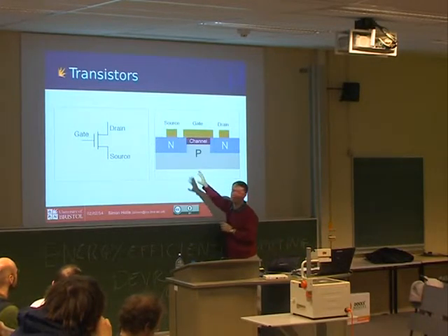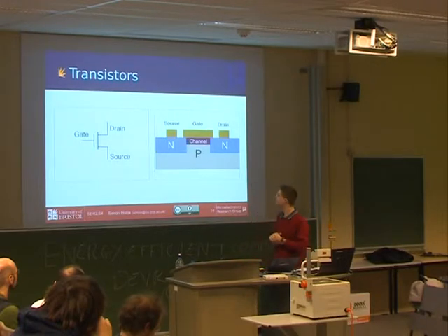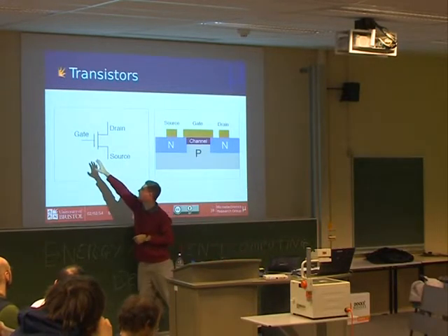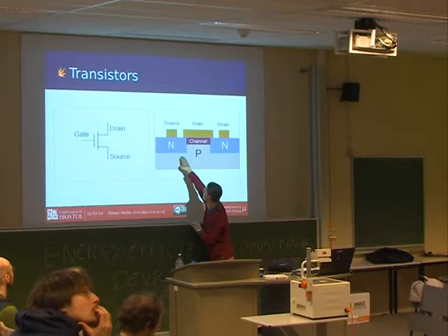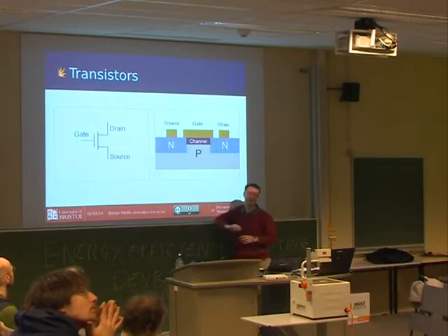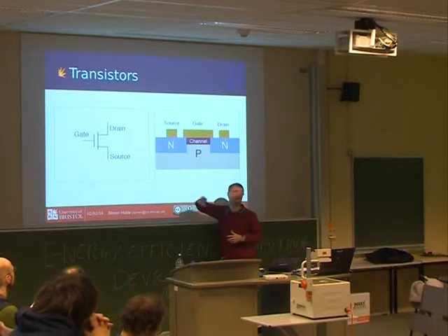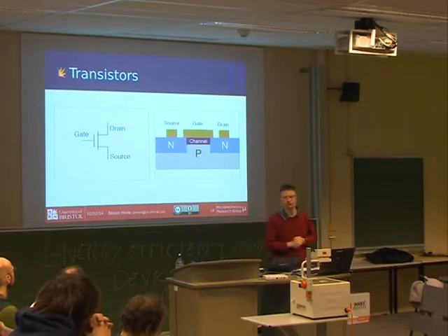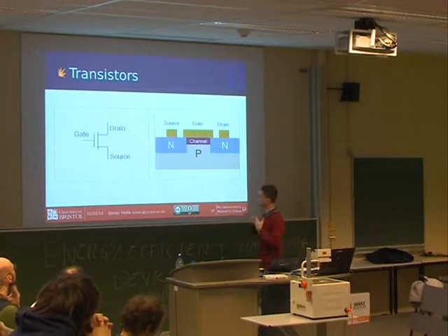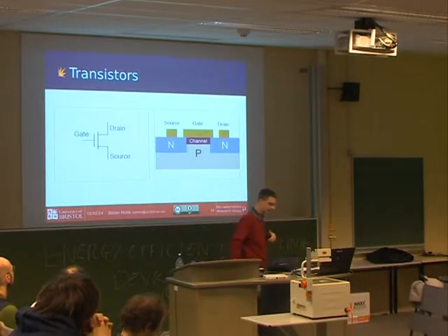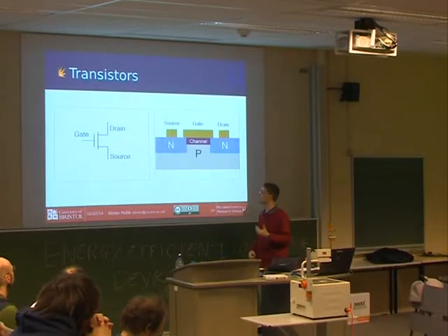So we've got two different types of silicon, two dopings of silicon here. And the idea is that this transistor will be able to be switched according to a voltage on the gate here, and if it's switched on, current passes between these two blocks of N-type silicon, and when it's switched off, current's not able to pass through that area called the channel, and that's how it turns off. So this is a device you can turn on, you can turn off, based on the voltage from the gate. And if you move the voltage from the gate, you will dissipate power.